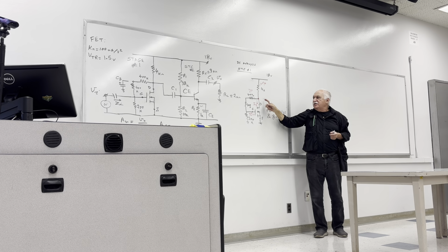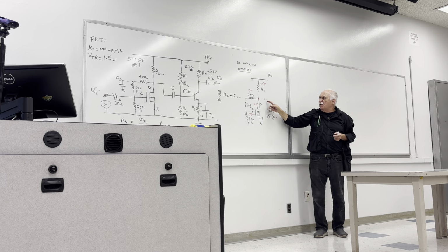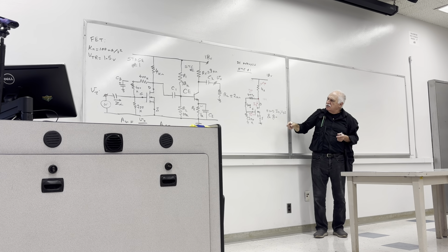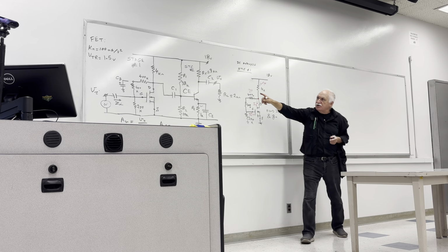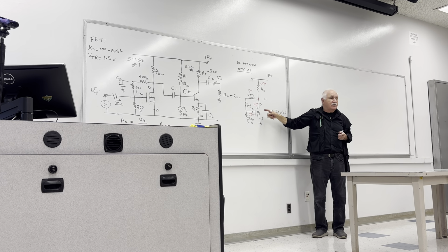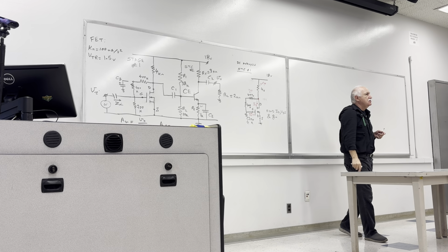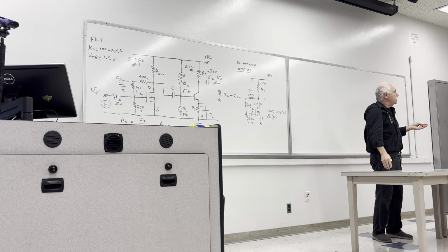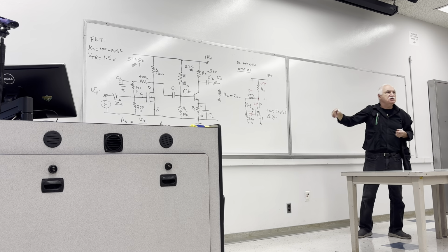Next, with a 10 volt over here, you're going to have, this is 2 over 800. This is like 1/5 of the 10, which is about 2 volt. It is greater than the threshold voltage, so we are going to see a significant milliamps in here as well, in the drain current. Out of the 3 currents, you notice that this one is the smallest, all right? So we are going to take it to our convenience and completely ignore it, as if that current is ignored.